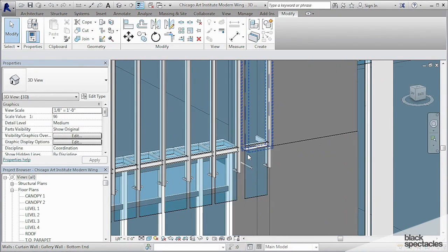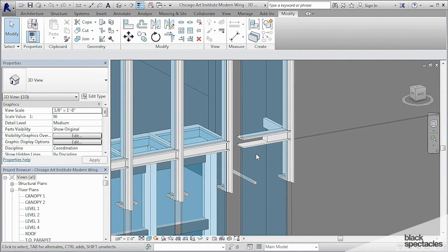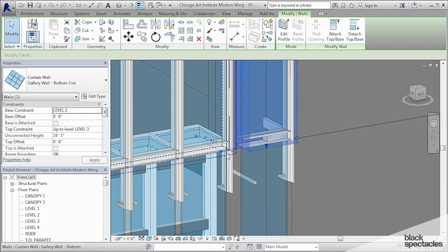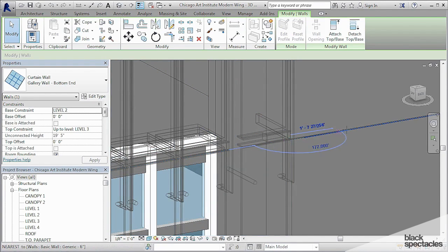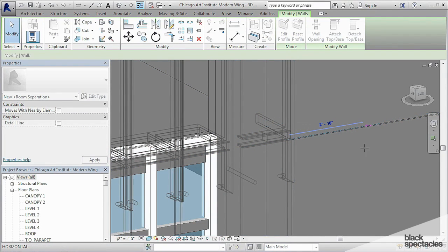And it's going the wrong direction. And this goes back to what I was originally talking about: how you draw the wall can determine what is left and what is right. Well, to flip this panel around, all I have to do is flip the wall around, like so.